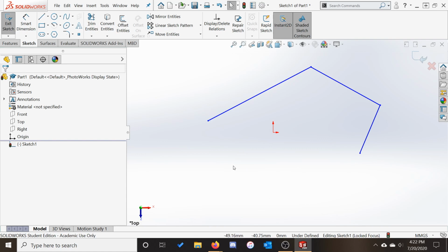These are based on the standard XY coordinate axes centered on the origin here. The small arrow points in the current X direction, while the large arrow points in the current Y direction. We can use these coordinates to place sketch geometry in approximate locations. In the next video, we will be detailing how to set and enforce specific dimensions and locations. But for now, these will do a good enough job in helping us get an approximate sketch down.